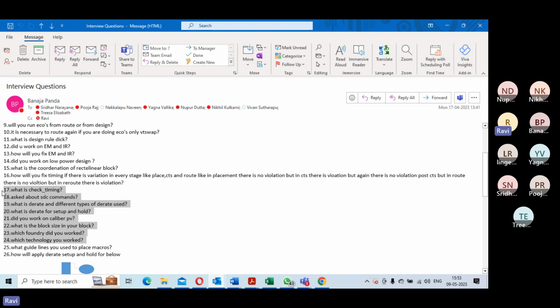In exceptions, you can look at multi-cycle path, false path, asynchronous definition. And also clock exceptions like exclude, stop, float. All these are clock exceptions specific to the clock tree. You can provide those things.